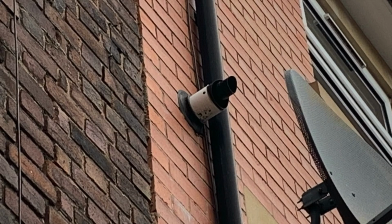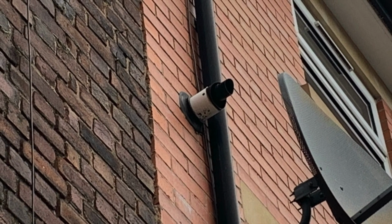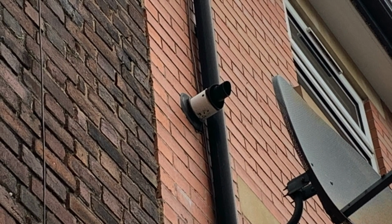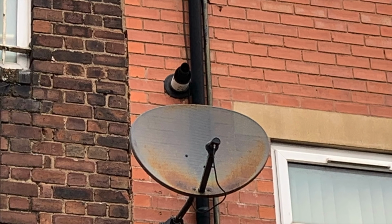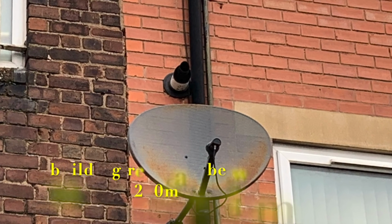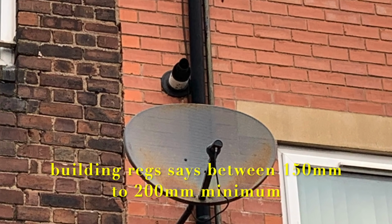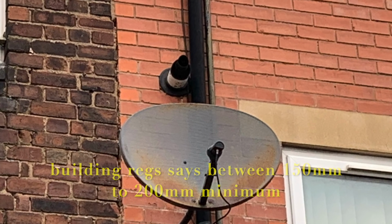Now this flue looks like a Baxi or an Ideal flue. According to the manufacturer's instructions for both those boilers, there should be no white showing on the flue when it's sticking out the wall. It should be more than 25 mil away from that downpipe. But again, this is just poor siting of a boiler. That would be the last place I would be looking to put it.